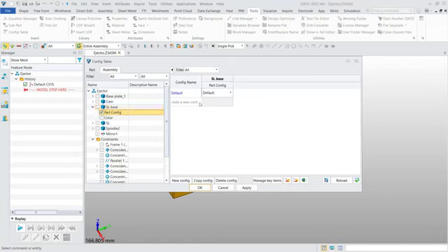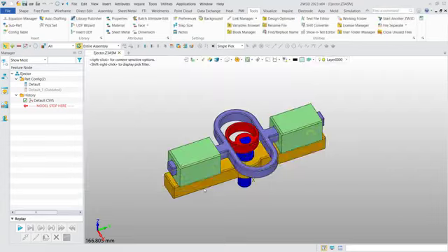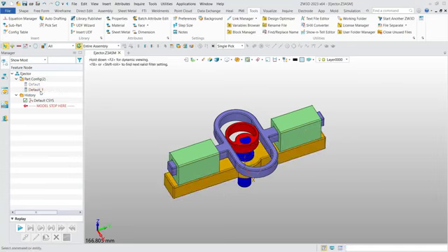For example, for the slider base, we have 3 configs here. We can create more. Copy. This one we make with width equals 20 and OK. Now you can see we have 2 different configs here. You can switch between them, and you can see it's changed. Then we can publish based on the 2 part configs.